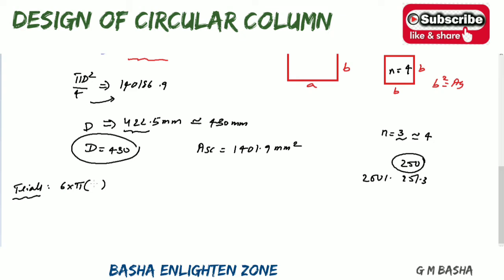So the minimum diameter bar required for the footing will be 12. If you choose 12, you will get a very minimum value. If you want, you can check that value. So therefore I am going to the next best value, which is 16. So diameter will be 16. So pi d square by 4. If you simplify this, my diameter here will be equal to 16. For this one, you will get around 1205.76 mm square. But see here, this is the required value for that particular column.